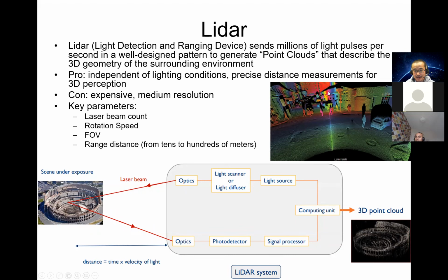So here's the point cloud collected by LiDAR. You can see rough shapes of objects, pedestrians, cars, buildings, and so on. So the colors are added later by the processing algorithm. So all you get back from the LiDAR are a collection of points. You don't know anything about these points unless you process them with perhaps machine learning, perhaps more classic computer image processing methods.